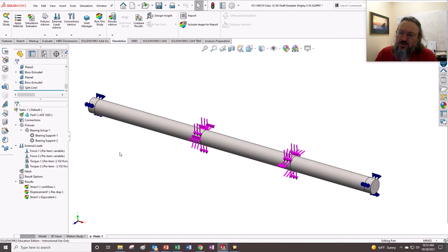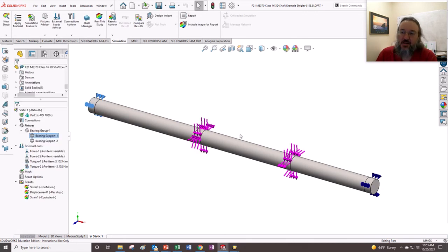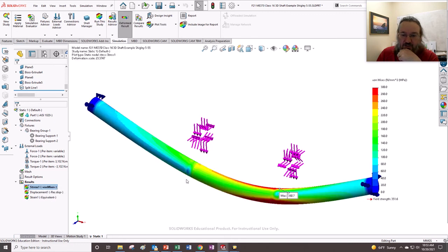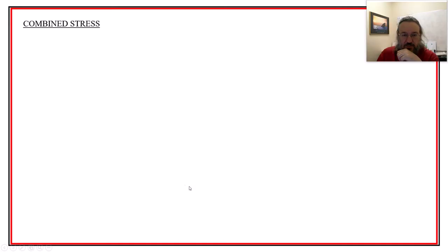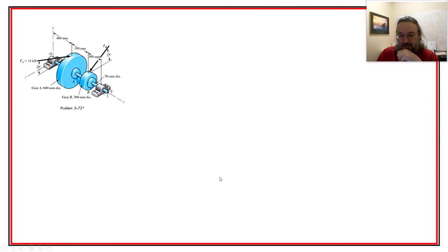I suspect but don't know that this one thing in the bearing support where they say stabilize shaft rotation might actually be that stabilizing thing. They might throw something in there just to prevent that numerical blowing up of the thing not being exactly equal. So anyway, I solved it, and I gave it a crude mesh, and you can see I get 380.7, whereas I was predicting, this is before the stress concentration, and this is von Mises stress.